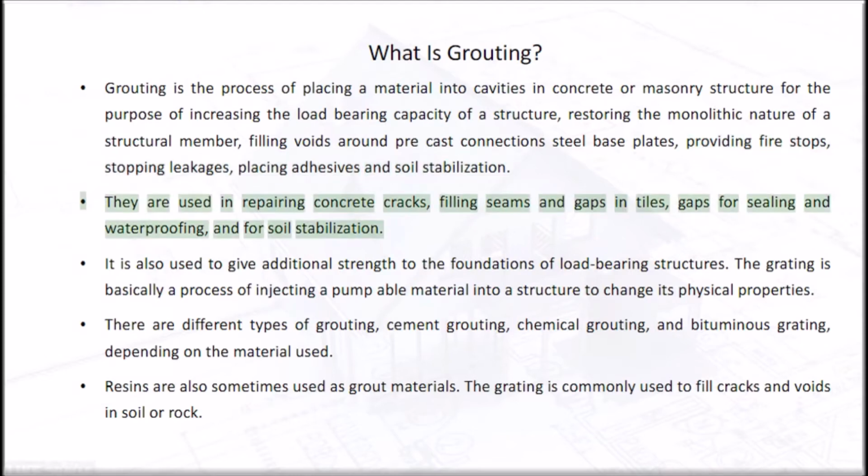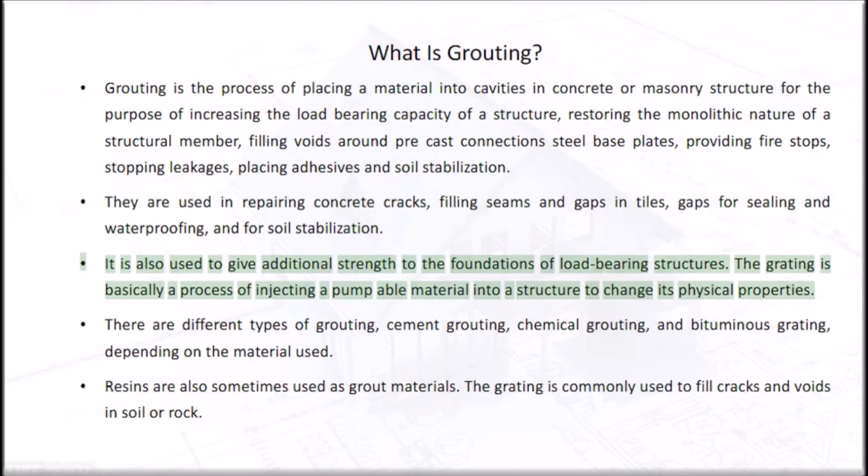They are used in repairing concrete cracks, filling seams and gaps in tiles, gaps for sealing and waterproofing, and for soil stabilization. It is also used to give additional strength to the foundations of load-bearing structures. Grouting is basically a process of injecting a pumpable material into a structure to change its physical properties.